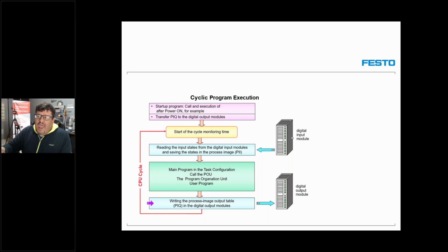It becomes a 1. Where did they store that bit, that value? That value is stored inside my PLC, inside the memory. It's called my process image input table. The memory for the output is called the process image output table.